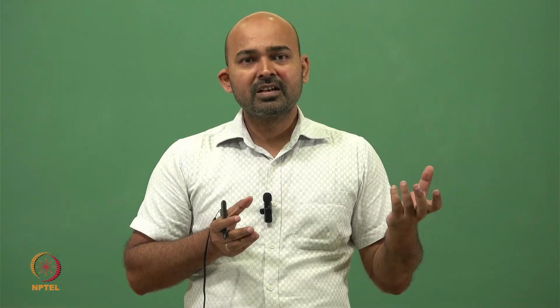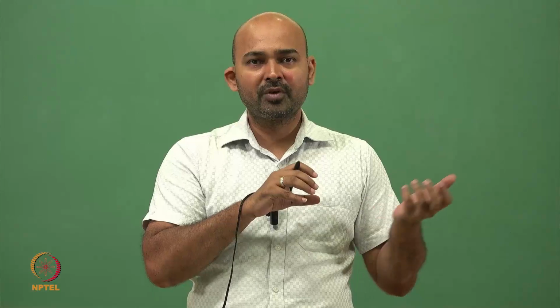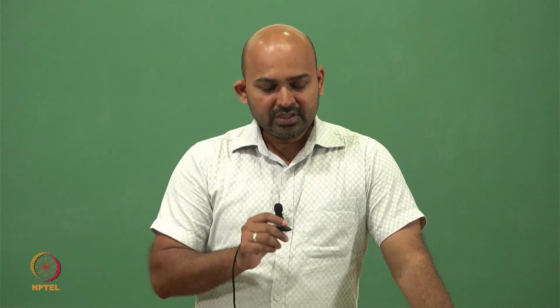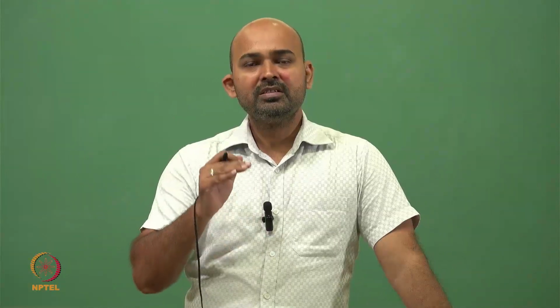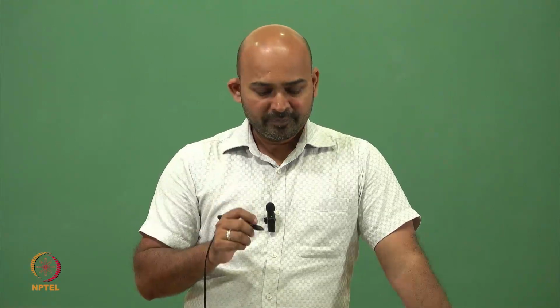Then the external circuit is applying a voltage on this pin, and Arduino is going to read whether it is 0 volt or 5 volt applied on that pin. So with digital write and digital read, the value can be only 0 or 5 volt.